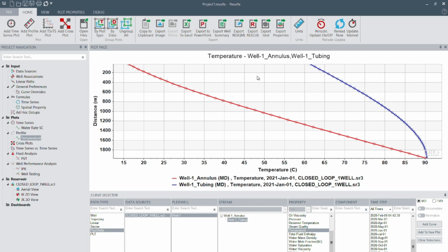The gap between injected and produced temperature of the water that's been injected and produced is of course a function of various parameters related to, for instance, the thermal characteristics of the well, heat conduction and heat capacity, but also we have an insulation string there, and we have input a thickness for the insulation string.